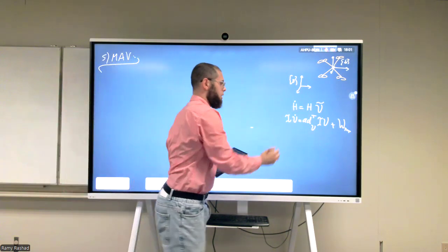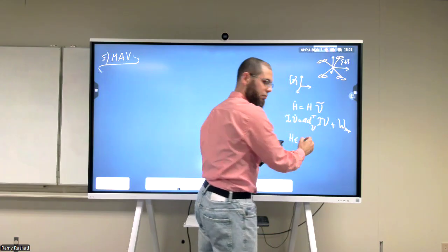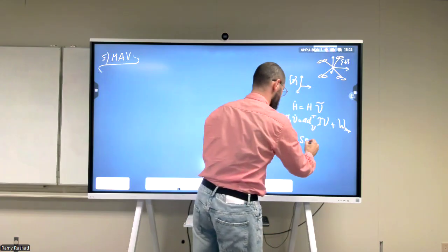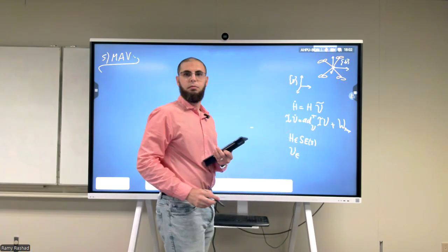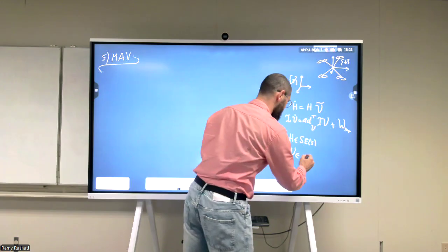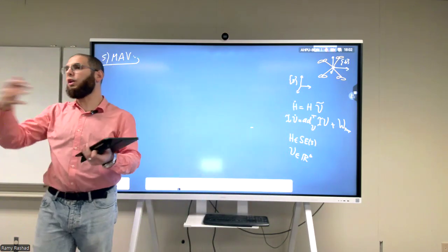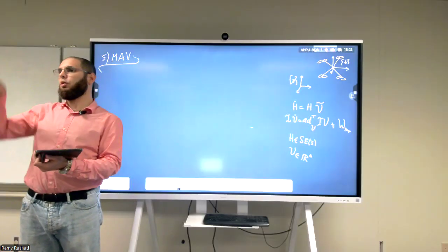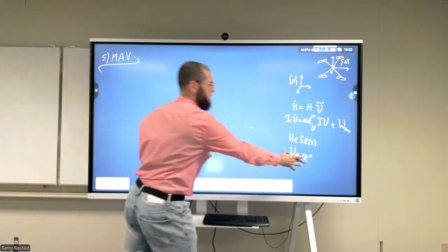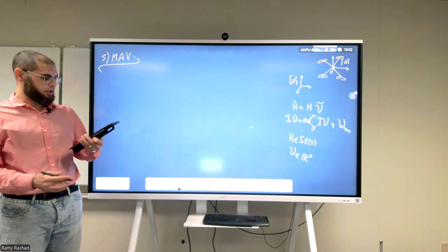And here v, so where does h live? SE3. Where does the twist live? R6, right? In the end, in the tilde form, it lives in the Lie algebra. But when we wrote it as 6 numbers, angular velocity on the top and linear velocity on the bottom, we just said it's in R6. You all agree? So this is the equation.